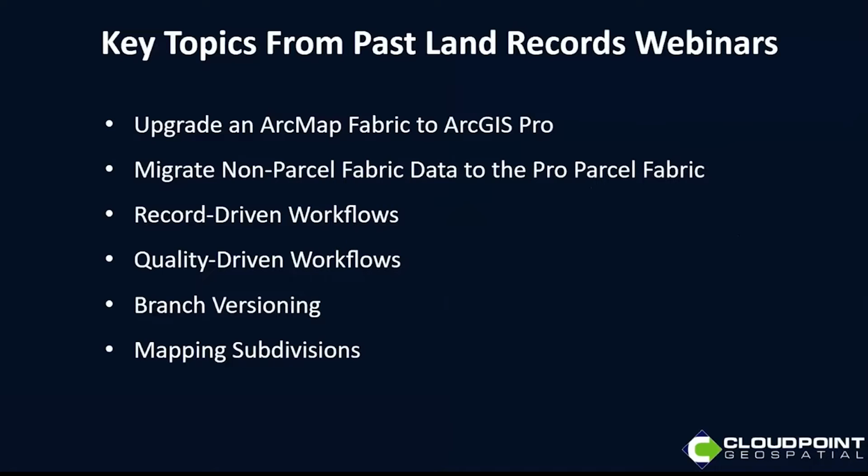All right, so a quick review of some past Parcel Fabric topics. Early on in this series, we talked about upgrading from ArcMap and then also migrating non-Parcel Fabric data into a Parcel Fabric. That led into record-driven and quality-driven workflows in ArcGIS Pro, as well as deploying the Parcel Fabric in an enterprise environment with branch versioning. Mapping subdivisions was a main topic at September's webinar and will be reviewed quickly today.